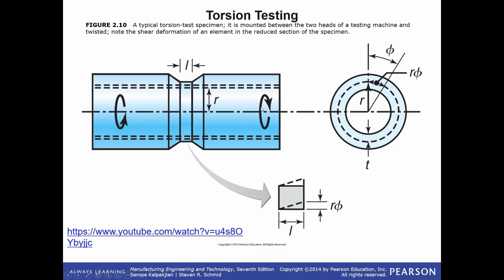So we spin this dowel, and the number of degrees it's able to spin gives us some information on how much loading it can take, under what load it starts stretching or plastically deforming, and then under what stress it actually snaps or shears. And again, there's another video here of a shear test, and I might try to click and clip these in my video when I go to edit, but most likely I'll just let you guys watch these yourselves.